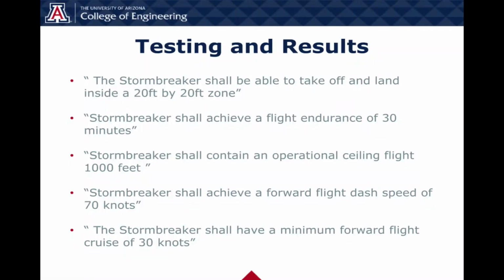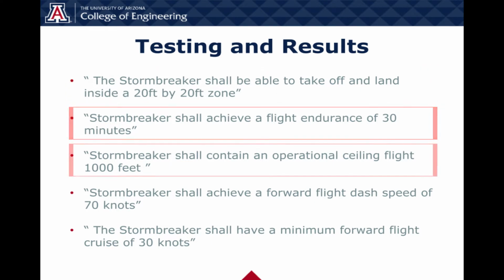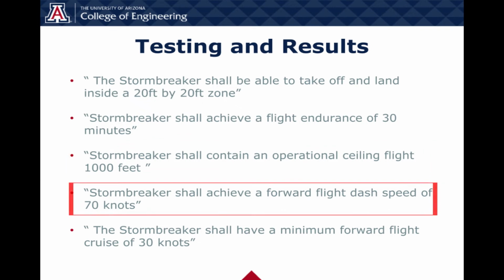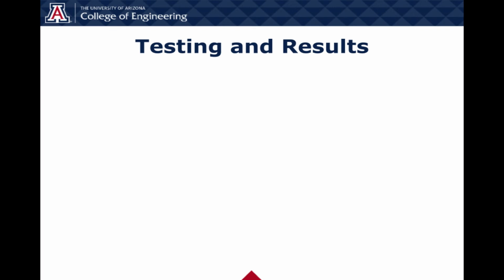We had 5 requirements that called for testing to verify: the ability to land in a 20-foot by 20-foot zone, a flight endurance test of 30 minutes, a flight ceiling of 1,000 feet, and flight speeds of 70 knots dashing and 30 knots at cruise.